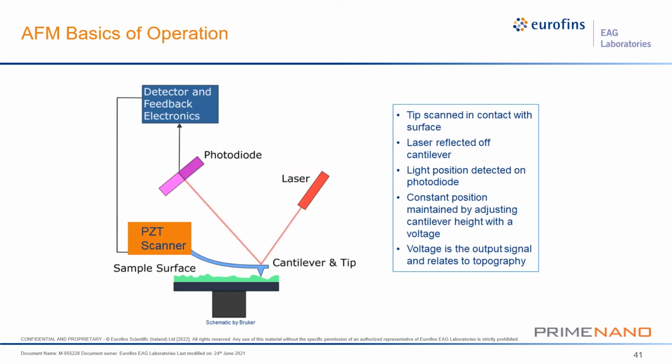SMIM is compatible with measuring a wide variety of material systems, ranging from dielectrics to semiconductors to insulators as well. Before we dive into it too far, it's an AFM-based technique, and the most basic mode for AFM is known as contact mode, and this is the basis for many electrical techniques like SMIM. The schematic on the slide shows the main components and configuration of a Dimension type AFM instrument. The probe consists of a springboard cantilever and a fine radius tip, and it's attached to a PZT scanner, which allows precise control of the position of the tip relative to the surface of the sample.